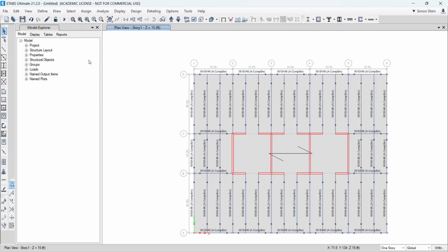So far we have basically practiced drawing the geometry using ETABS. You got that up to here? We didn't do any engineering, just based upon an understanding of the structural system and background, we laid out the vertical elements, which are columns and walls, and beams.